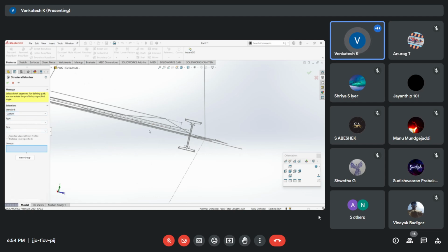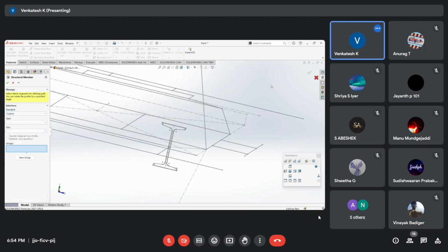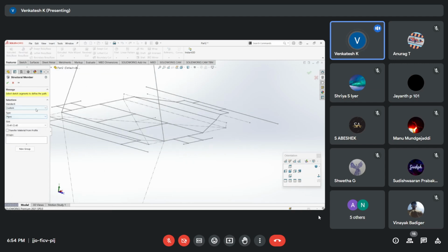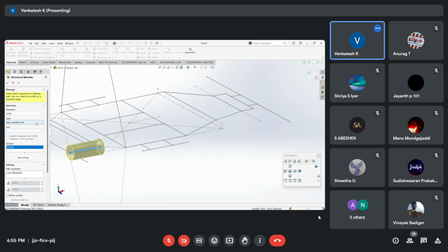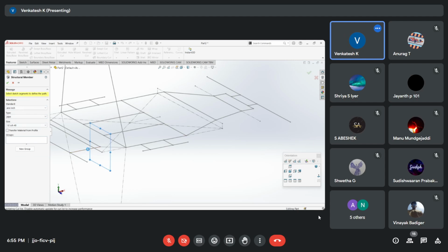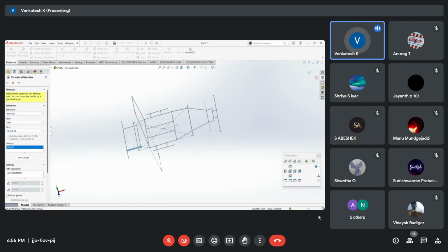I mean, we have to design our custom pipe such that it meets our actual design in the lab. So we should make our custom pipes, but for now we'll just use an ANSI standard pipe, the pipe of S40, I guess. Yeah, okay, that's true. ANSI inch, and clear everything. Let's go with the pipe. Size will be 1 inch. Yeah, this will be a 1 inch pipe.